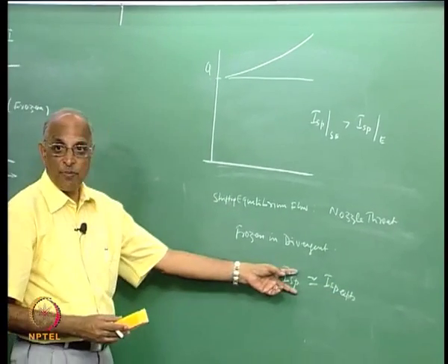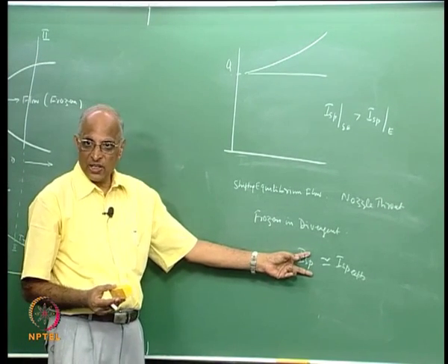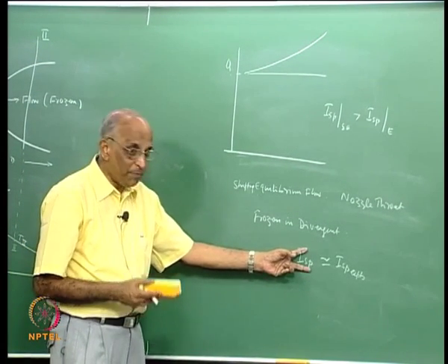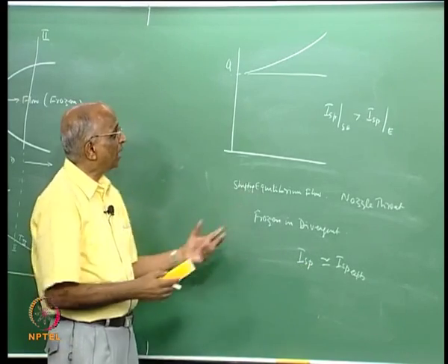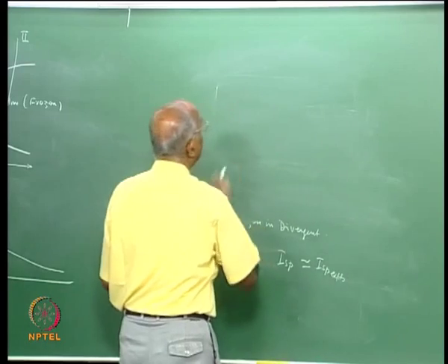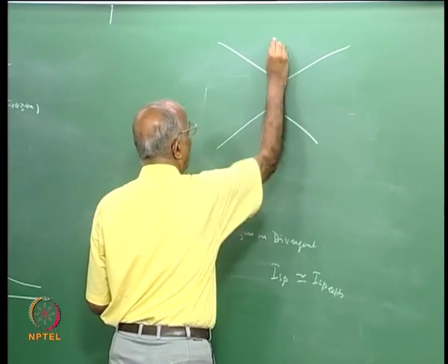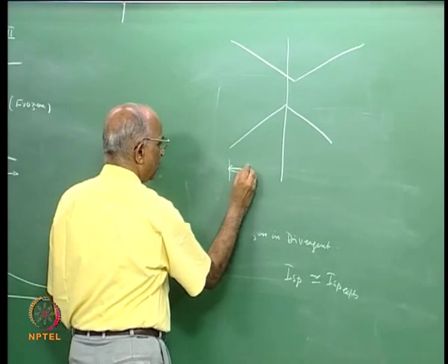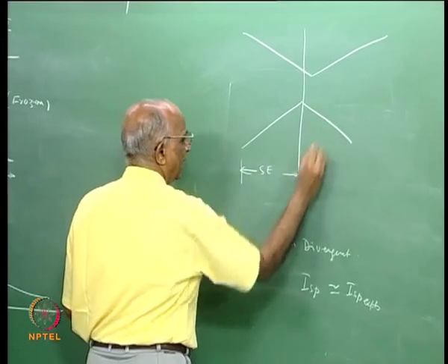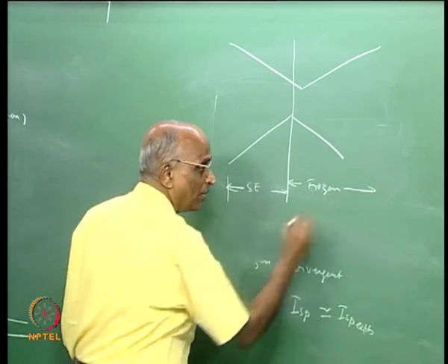It depends on the type of gas, the type of dissociation, but for hydrogen oxygen there has been published work, they have the Bray model and all that, which assumes, let us just put it down, supposing I have a nozzle, convergent followed by divergent, I have in the convergent shifting equilibrium flow and in the divergent frozen, which tends to give me a reasonable value.